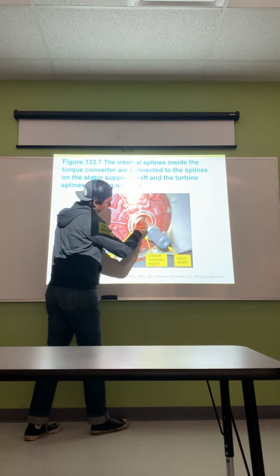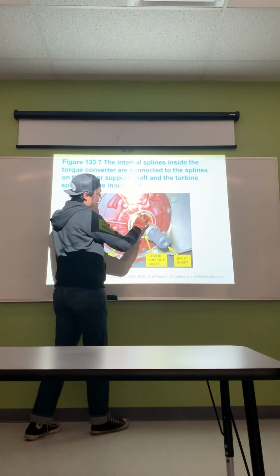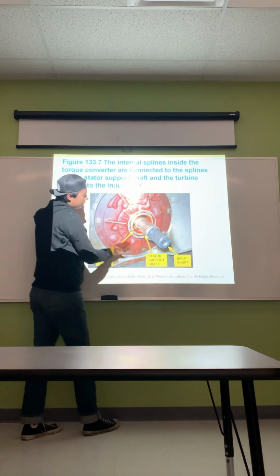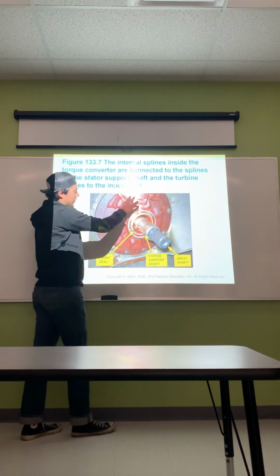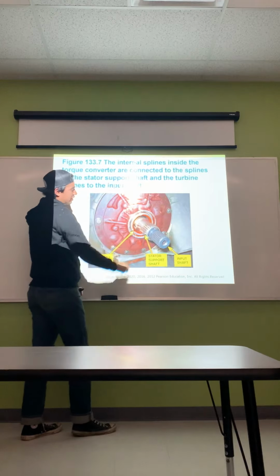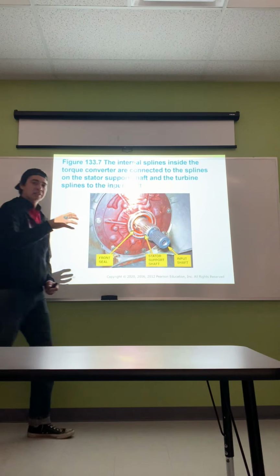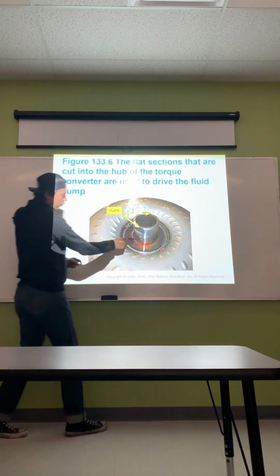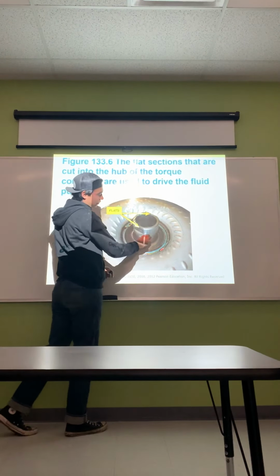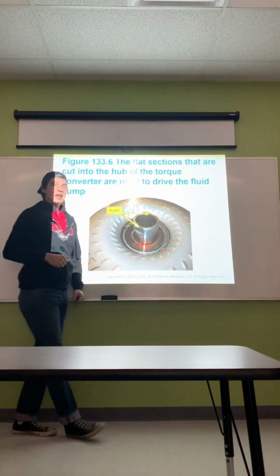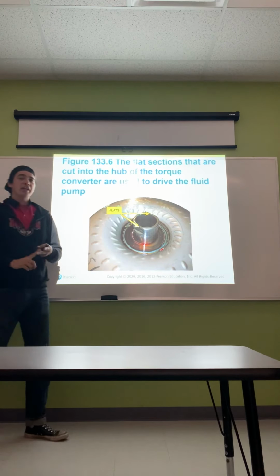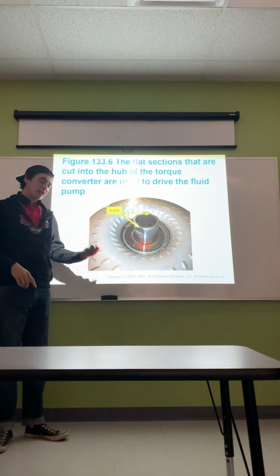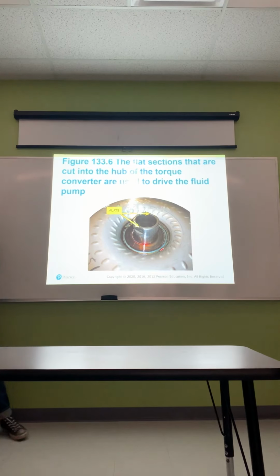Inside here, you'll see the small grooves where the pump is actually going to be engaged. This section here is actually the pump. Not only is it the pump, but it's also where you're going to have your sealing for the actual torque converter being inside. So when installing a torque converter, you want to make sure that this portion here is nice and smooth. If you have little gouges and cuts and nicks, it can cause it to not seal properly, or it can actually damage a brand new seal, which it eventually will leak as well.